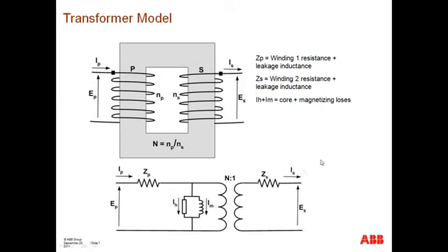Since there's nothing connected on the secondary winding, there's not going to be any current contribution from winding 2. Thus, essentially, whatever current is flowing through winding 1 is going to be interpreted as differential current, and as an internal fault occurring inside of the transformer. And this is because of the magnetizing branch.